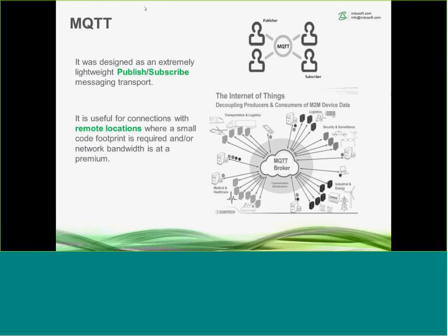Talking a little bit more about this protocol, it's actually designed to be very lightweight, and it's built on a model called publish and subscribe. That's a little bit different than master-slave or, if you've used DeviceNet, consumer and producer, those types of things. It's similar in idea, but the way that I like to look at this is the publisher is doing the writing to the broker, and the subscribers are then coming along and picking that up.